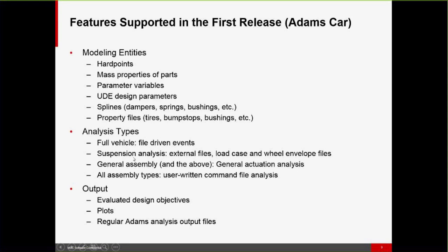And then analysis types here, we're supporting file-driven events right now for full vehicle analyses, a number of analyses for the suspension, and also general actuation analysis, and user-written command file analysis. And then in terms of output, pretty much the same thing as what we saw in View: design objectives, some plots from a plot configuration file, and again, all the Adams files will be available.